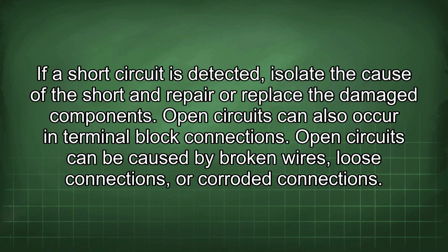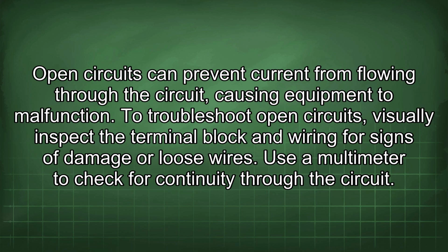Open circuits can also occur in terminal block connections. Open circuits can be caused by broken wires, loose connections, or corroded connections. Open circuits can prevent current from flowing through the circuit, causing equipment to malfunction.